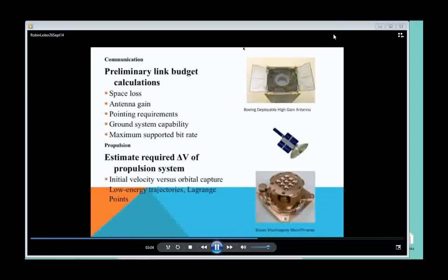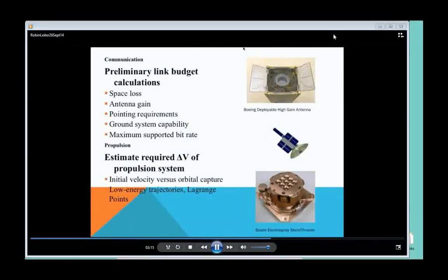The propulsion page estimates the required delta V for a CubeSat's proposed trajectory in orbit using low-energy trajectory estimation. It compares these requirements to existing CubeSat propulsion systems such as plasma and chemical thrusters and air brakes, and displays their nominal, specific, and total impulse and delta V if available.